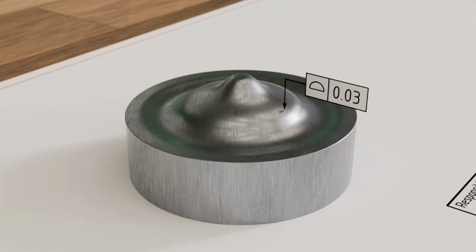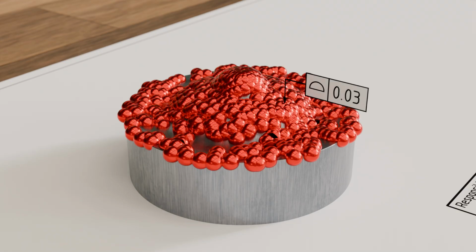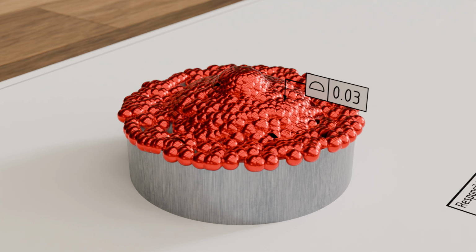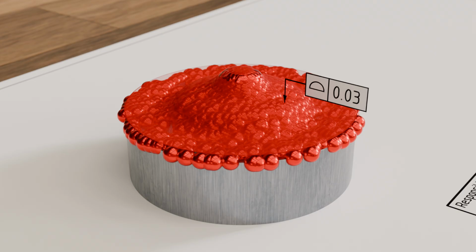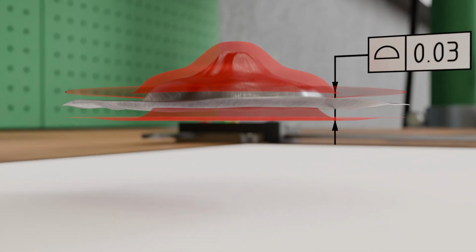For such surfaces, in addition to the profile tolerance for arbitrarily shaped lines just explained, there is also a profile tolerance for arbitrarily shaped surfaces. In the feature control frame, the open semicircle is then shown as a closed one. The tolerance zone is obtained by imagining infinitely many spheres with a diameter equal to the form tolerance value, whose centers are distributed over the tolerated surface. The envelope of these spheres on the upper and lower sides corresponds to the form tolerance zone. The actual surface must then lie between these equidistant boundaries.